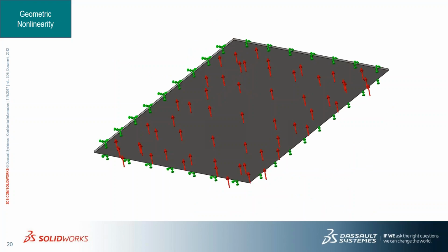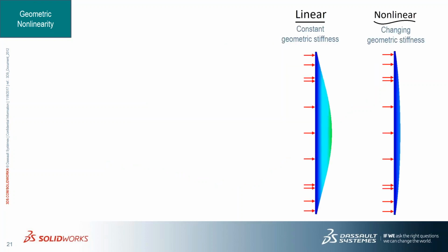Then finally, let's talk about stiffness changing. This happens a lot in thin wall structures. So if you have a sheet metal part surrounding a hopper that's going to be filled with plastic pellets, or like a milk jug, anything that's going to be filled, a container that's filled with something that will exert pressure on those outer walls, this kind of behavior you may need to account for. So any thin-walled structures. This behavior I'm talking about is stiffness changing.